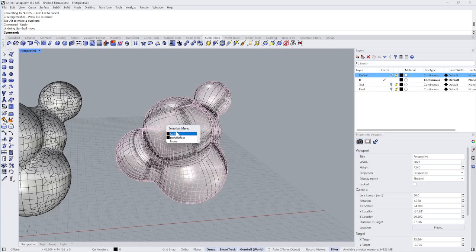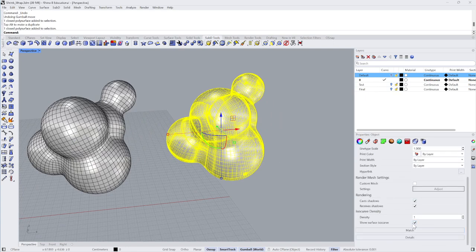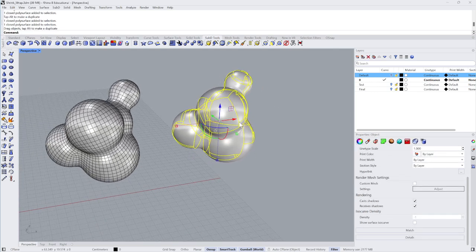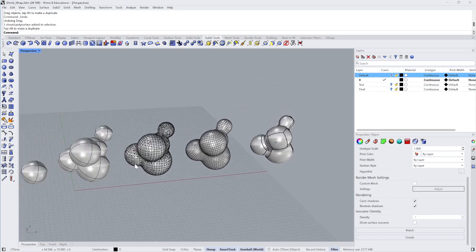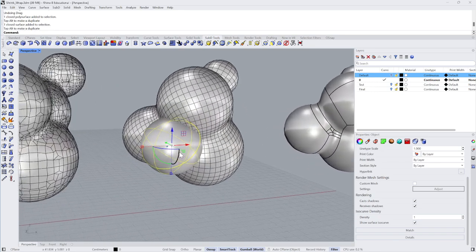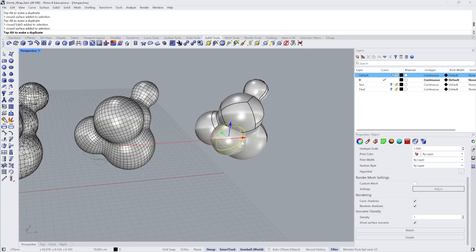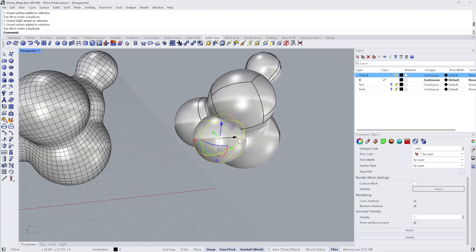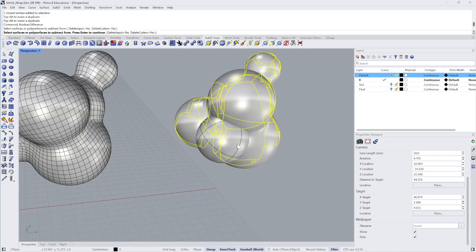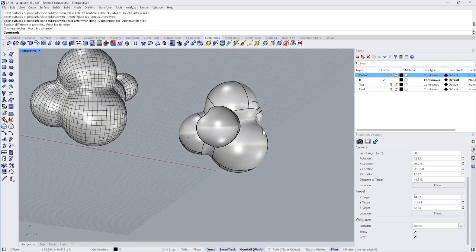Oops, I want to pull the other one. Let's grab the polysurface. That's our NURBS. So we get these NURBS patches, and now we could use all of the nice NURBS commands on this, including Boolean. So it would be very difficult for me to, let's say, take this sphere, NURBS, sub-D, or otherwise, and Boolean it out of this sub-D object. But what I can do is come over to this, use my Boolean command, Boolean difference. Take this one, enter this one, and now I've carved that out.